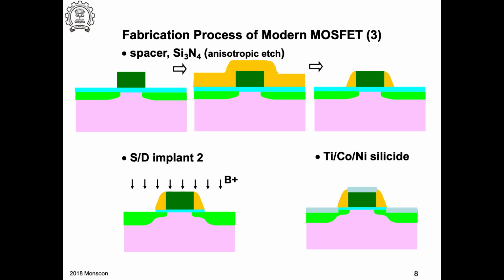No, see, if I have a very thick mask, everything will be inside the mask. So you can see it here. So this is my profile. I'm talking about 3 orders of magnitude difference. So this is 2 into 10 raised to 18, and I'm talking about 2 into 10 raised to 15. So the mask should be thicker than this. About 125 nanometers. Yeah, 125 nanometers. So this is the line that you're talking about. We'll come to some value.